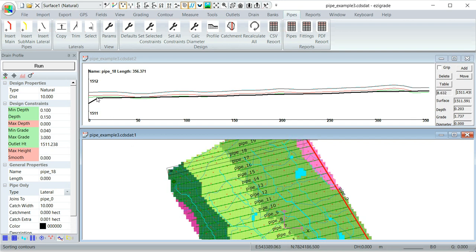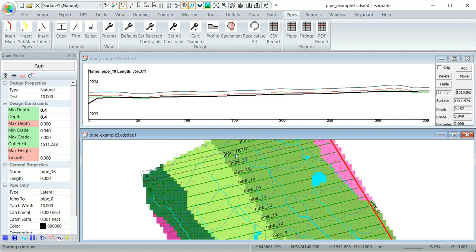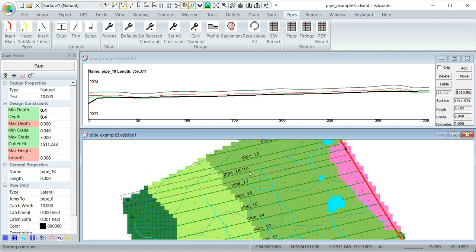if you look at that, say looking at pipe 18, assume we say something stupid, so we want the minimum depth to be 0.4 and that depth to be 0.4. No, that's impossible, so we'll just run it. Oh, it tells you there's no optimal solution. It's changed. So there's no solution on pipe 18. So yeah, that's what happens if there's something out.